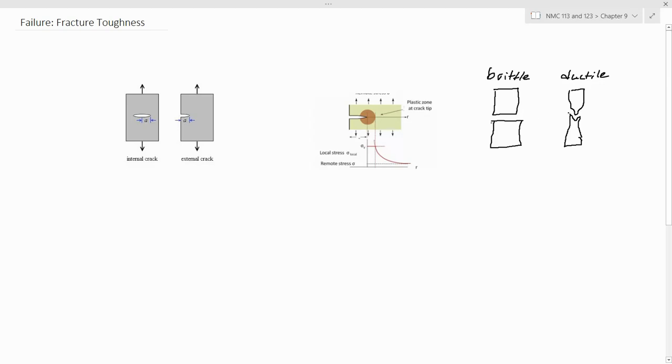material. So basically, fracture mechanics relates the material's properties, stress levels, and size of crack producing flaws. Crack producing flaws are like sharp edges inside the material, because we know that there's no material that's perfect. So internally, for example, during a steel making process, there's going to be some voids inside the steel.